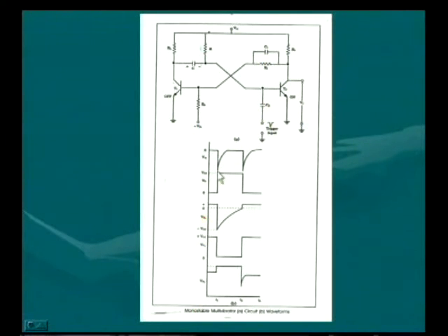So whenever we apply a negative going pulse to transistor T2, it changes its state from on to off. At the same time, the output of the first transistor changes from off to on, and this one is the input voltage to the base. So here we can clearly see it will be forward biased for the time during which transistor T2 is on.